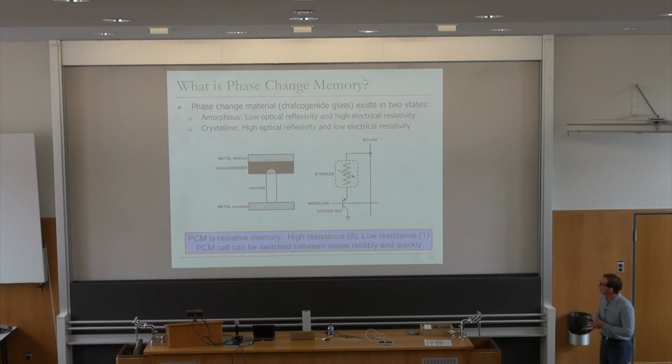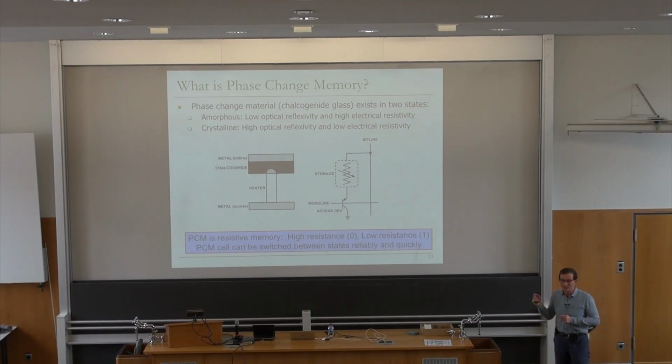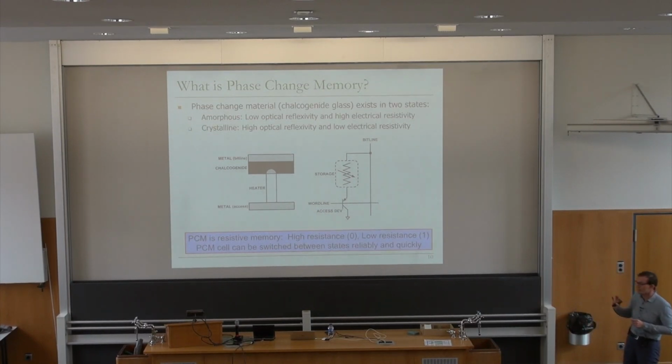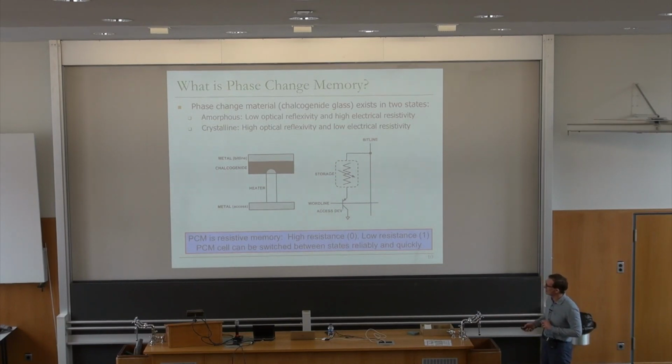Basically, what has happened in relatively recent years is people invested a lot into developing read devices, basically devices that can detect the resistance of what is stored in the storage device. There's a lot of work in this area. IBM has done a lot of work especially. You can find some of that work in that paper that I mentioned, but there's a lot of work since then as well. And people were able to develop very reliable and very fast read devices. You can think of them as sense amplifiers, kind of, but they detect the resistance so that they can detect whether you're in the amorphous or crystalline state, or what resistance range you are in. And that's fascinating by itself, but that's a very long, low-level lecture, which we're not going to get into.